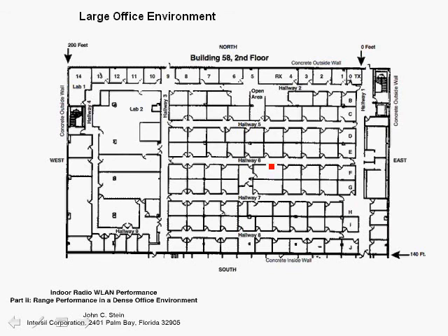Now, the multipath environment depends on where you are. Large hallways actually create a waveguide effect, and you have beams that scatter energy from the wireless communication link, and you have multiple scattering sources. You have shadowing effects. You have penetration, for example, through the floors to the lower floors, etc. So many factors will impact the fading multipath channel.